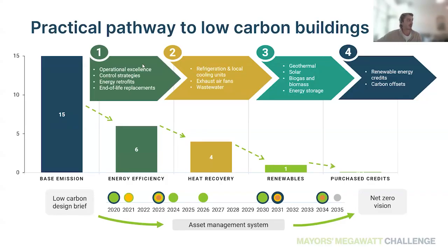Once you have that in place, you would look at the more capital measures. That's upgrading your fuel-fired RTUs to either high efficiency or, ideally, some form of electric air source heat pump unit to really target the greenhouse gas emissions reductions. So we've made sure the building's operating as efficiently as we can in terms of operations, and then we've upgraded and replaced equipment at its end of life with higher efficiency options.